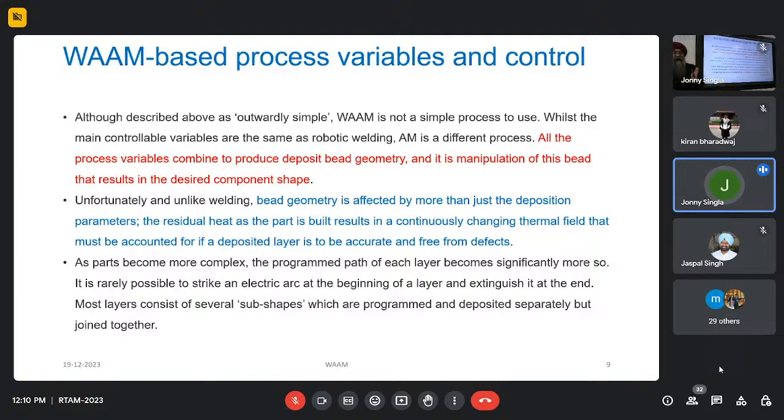Now, if some kind of deformation occurs in, say, your component that is visible to me through visual inspection, I can make out that something is not in conformance with the desired geometry, but as far as residual stresses are concerned, it is very difficult to predict. With the naked eye or with the visual inspection, I cannot judge or predict what kind of residual stresses would be built.